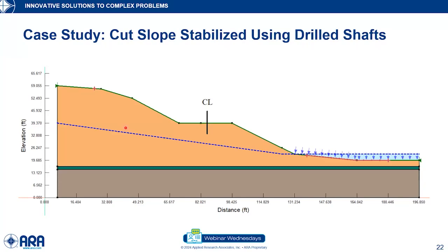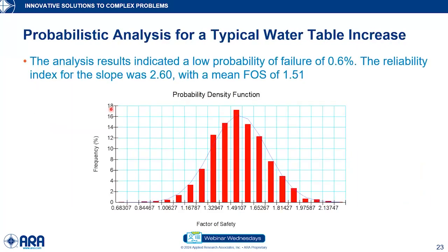So when you have repeated events, the overrun reduces and they are short, not necessarily flood events. So your riverbank doesn't go up and then start flooding the other assets. It's the other way around, where you have repeated rain events slowly, day over day, and the soil in here gets saturated over time. You don't necessarily see any warning signs of flood, but all of a sudden, at some point, your water table goes up and leads to a failure.